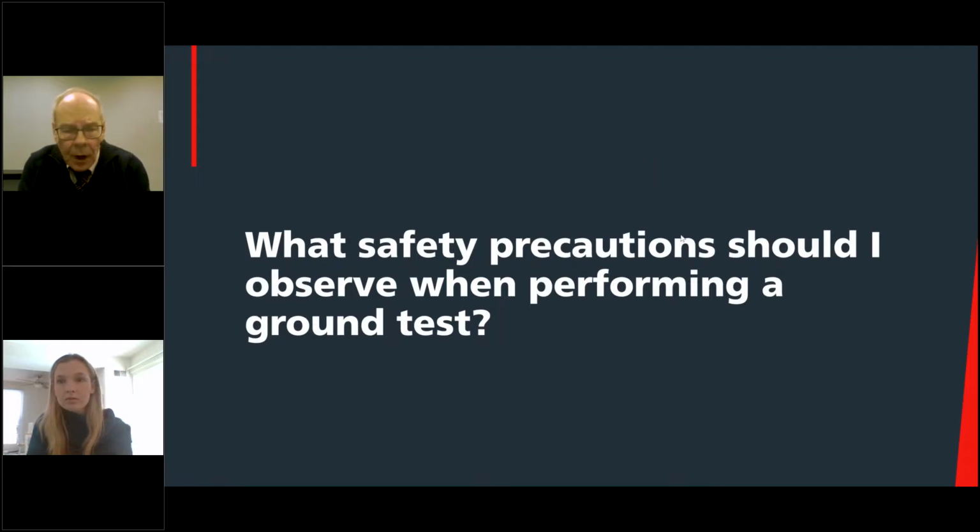You want to use basic protective equipment, particularly what you're wearing, gloves, boots, and also you can work on a grounding mat. The tester itself does not have enough power to injure you. A ground tester needs very little voltage and very little current to operate. And so the tester itself is not dangerous.